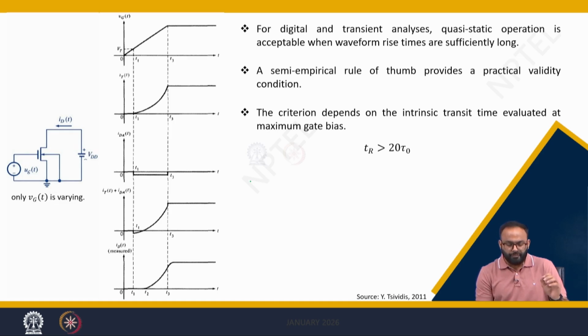So we can again argue what the problem with the quasi-static model is. The first thing is, we discussed that there is a negative current coming in, which we are modeling, which our model shows. However, the experimental data does not show that because of the transit time issue. Now this negative current, which we are saying is a charging current at the drain and source side, is dependent on how you distribute this charging current.